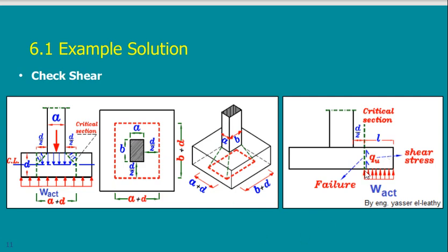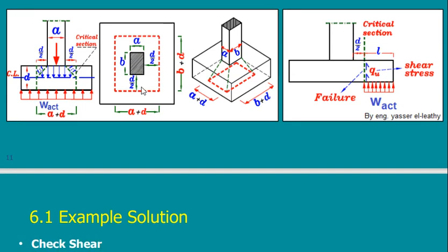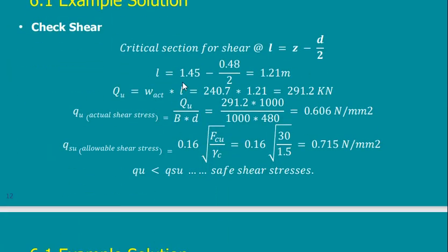But I can work with the thickness and increase it. You will end up with a higher allowable, so it will be safe. That's why we said don't calculate the steel now, wait, because we may increase the D during the check of shear, or during the check of punching that will follow. So this is an equation.